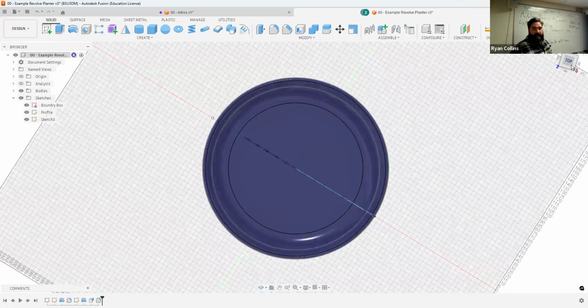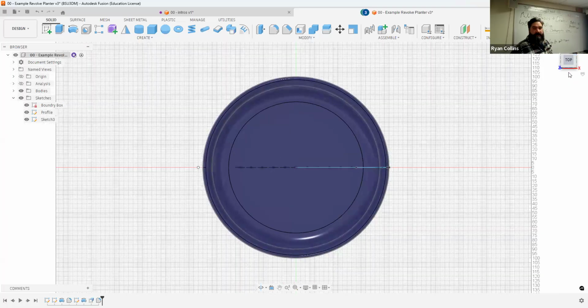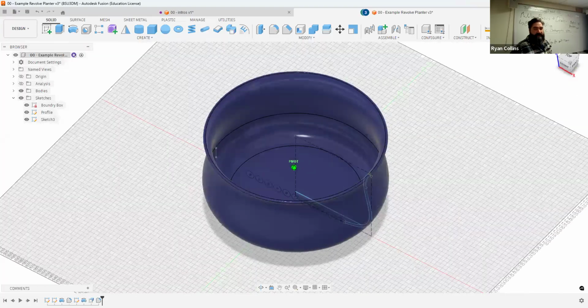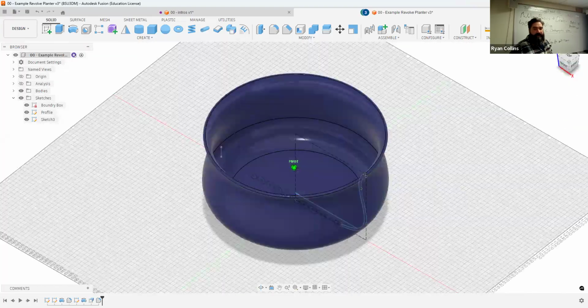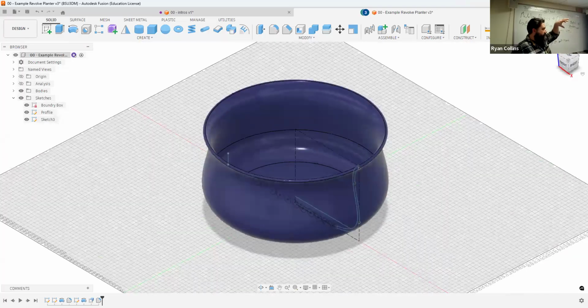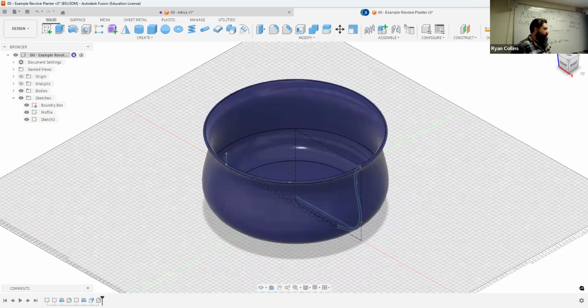You can rotate it. You can use the little clicks here, cycle around, and at any point you can click and drag the thing. One of the other things you have when you mouse over this view cube, see this little house symbol? That will be the home key. When you click that, it snaps back to that kind of perspective isometric view. That's one of your standard ways of moving around. It's probably one of the easiest.